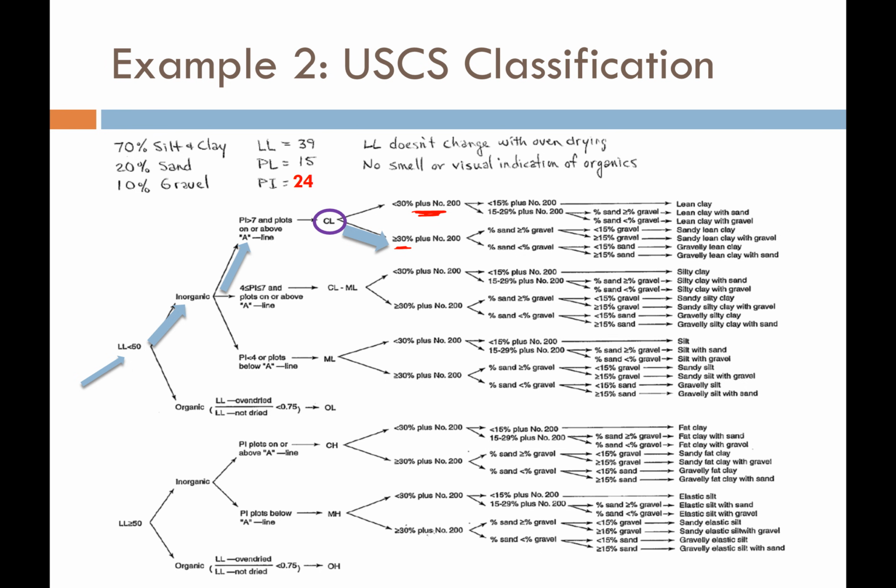Now, is the percent sand greater than the percent gravel, or is the percent sand less than the percent gravel? The percent sand is greater than the percent gravel. Do I have less than 15% gravel or more than 15% gravel? I have less than 15% gravel. So here's the name of my soil: sandy lean clay.